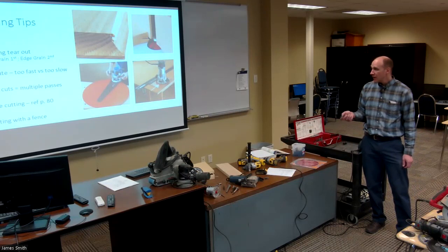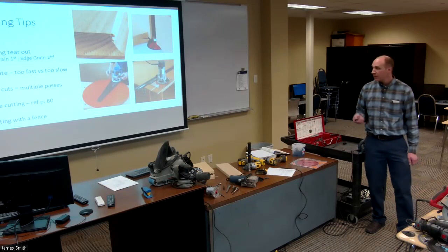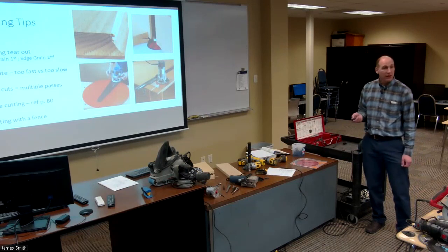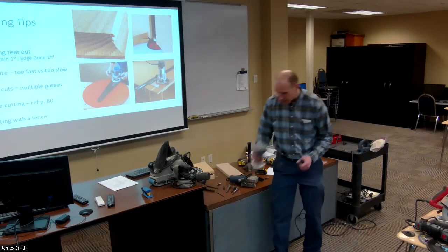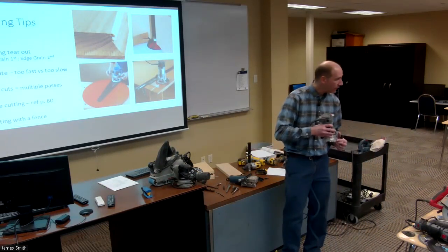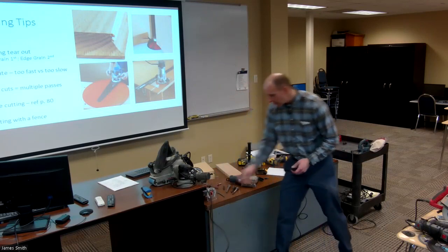And then if you've got straight dados or rabbets that you need to do, you can use a fence. Okay, I've done that a lot, where a lot of these routers will have a flat edge on the base, and you just run that along the fence. And so that's kind of a nice feature that way.